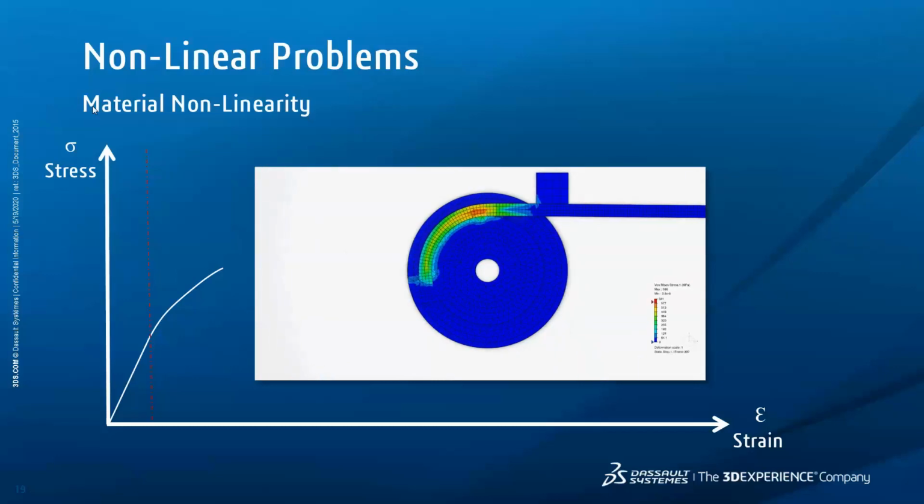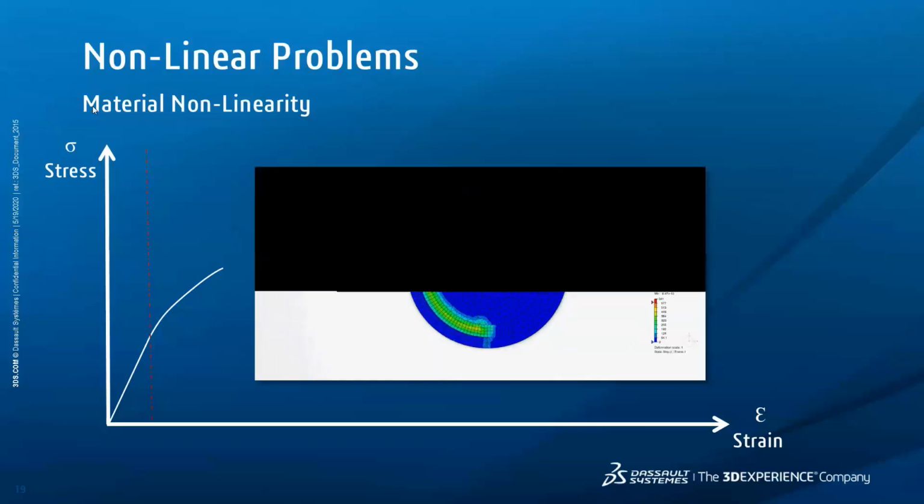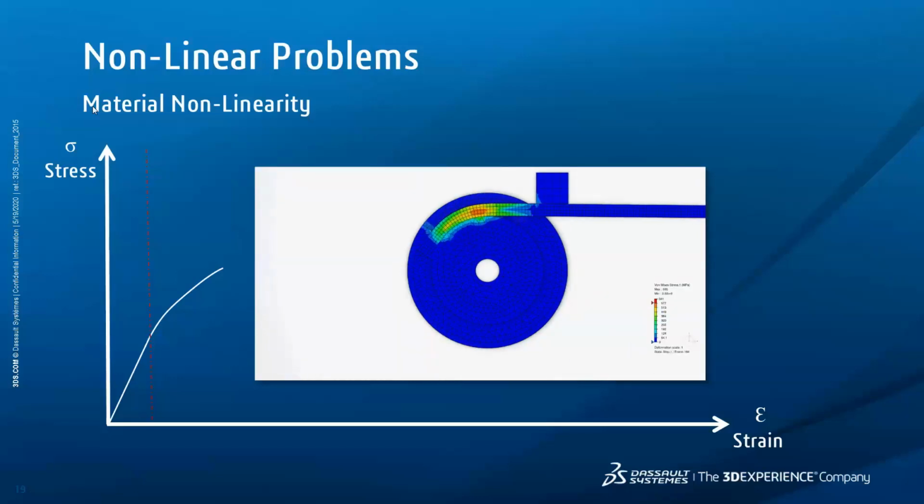As strain rates increase, many materials show an increase in their yield strength. The effect becomes important in many metals when this strain rate range is between 0.1 and 1 per second, and it can be very important when they range between 10 and 100 per second, which is very characteristic of high energy dynamic events or manufacturing processes.